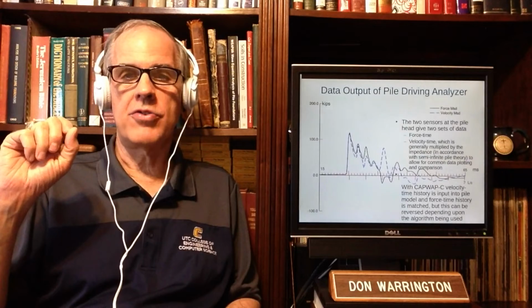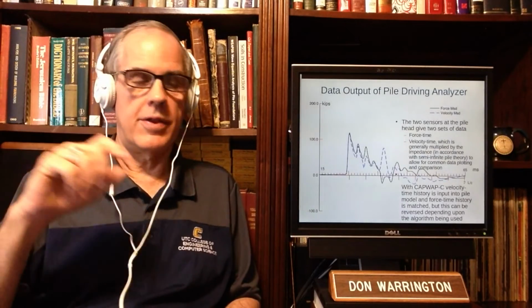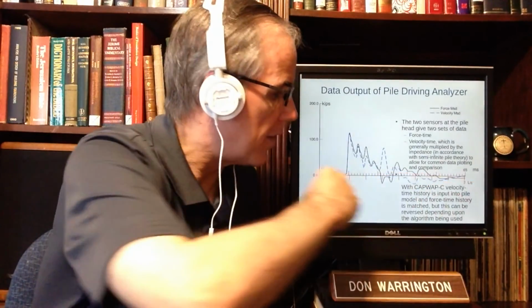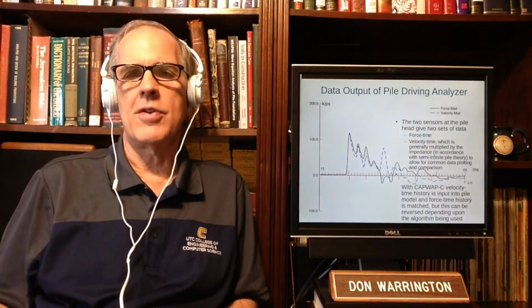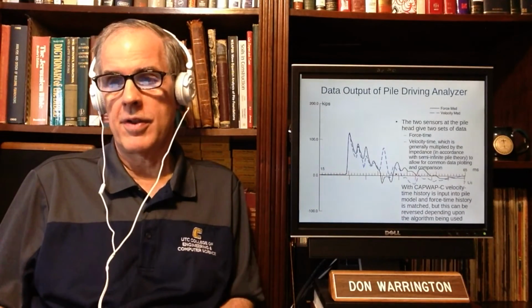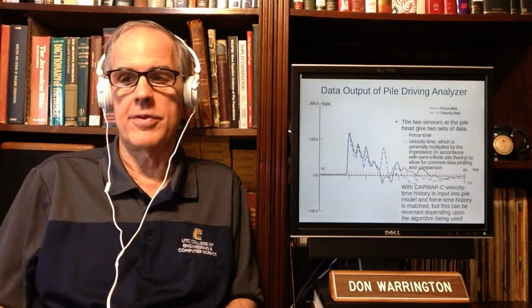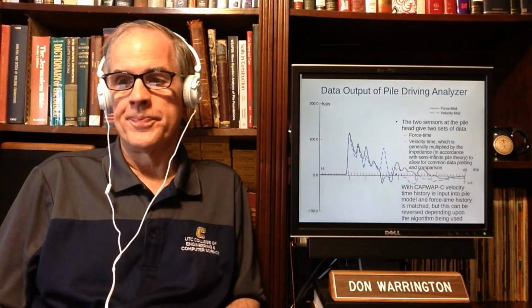And traditionally we measure this either in milliseconds or L over C. L over C is more convenient, or both, as you see in this case. Like I said, this came from an actual CAPWAP analysis. The force versus time is the solid line, and the velocity versus time is the other.